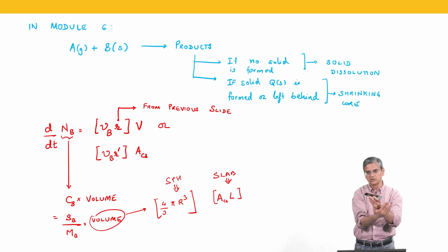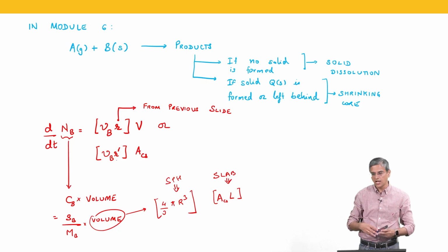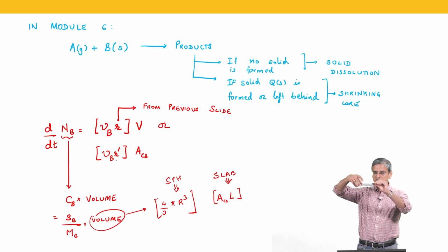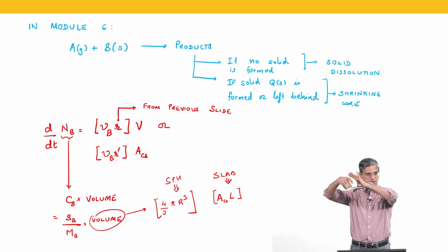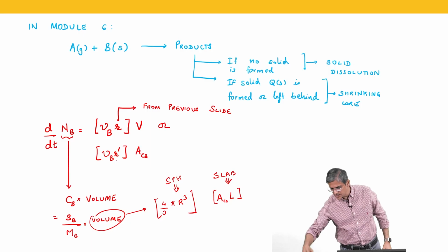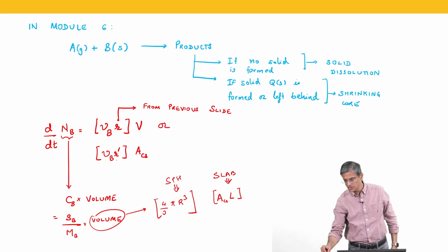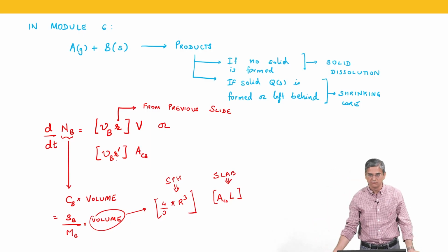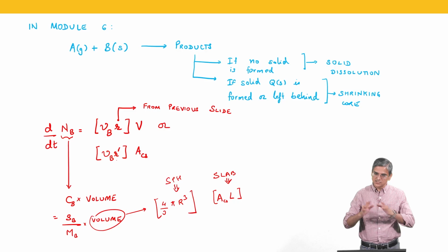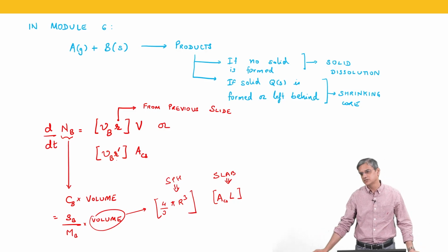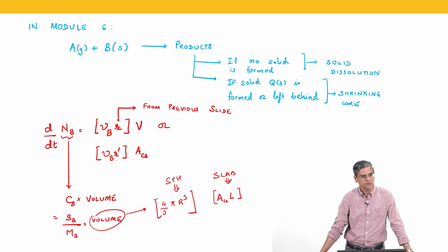Okay. That is how you want to analyze the slab. If this is a slab in the fluid, half of this is your L. If this is a slab where only one side is the fluid, the entire thickness is your L. That is for your convenience. If you want to take the entire thickness as L and do the analysis, all the analysis works fine as well. I am just talking about how the analysis is done in your textbook.